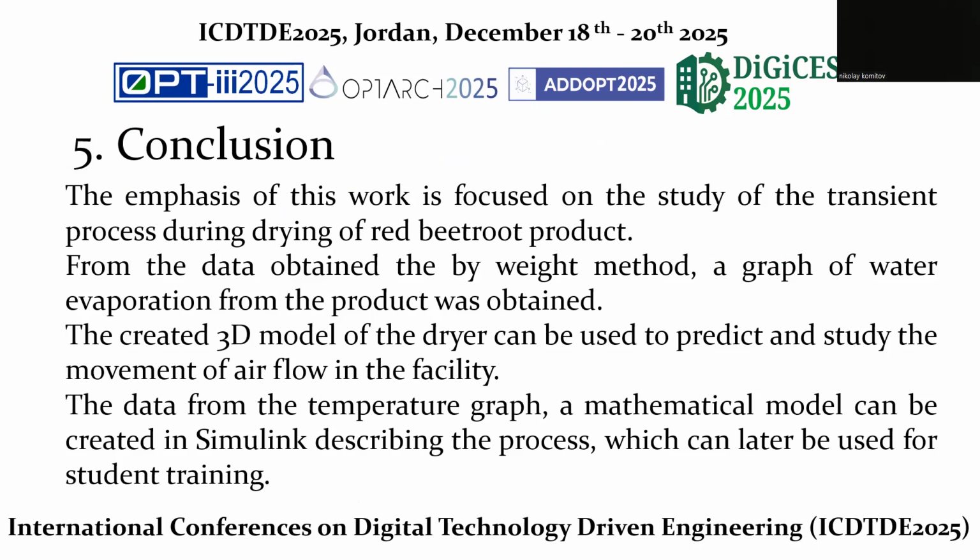Conclusion: the emphasis of this work is focused on the study of the transient process during drying of the red beetroot product. From the data obtained in the weight method, a graph of water evaporation from the product was obtained. The created 3D model of the dryer can be used to predict and study the movement of airflow in the facility. From the data of the temperature graph, a mathematical model can be created in Simulink describing the process, which can later be used for student training.